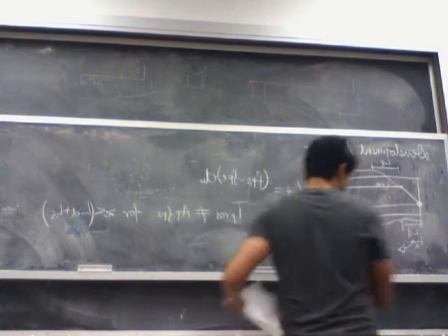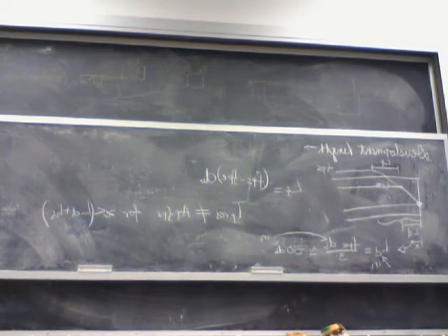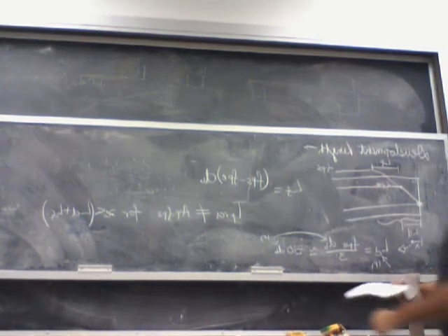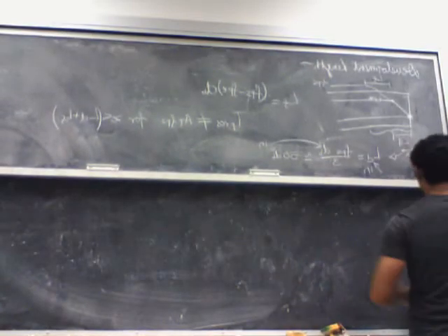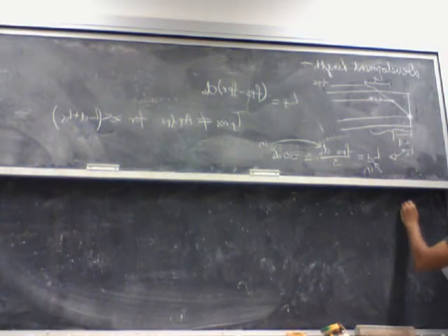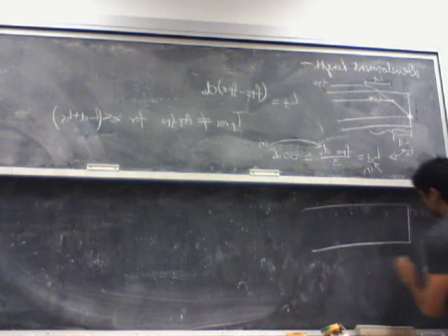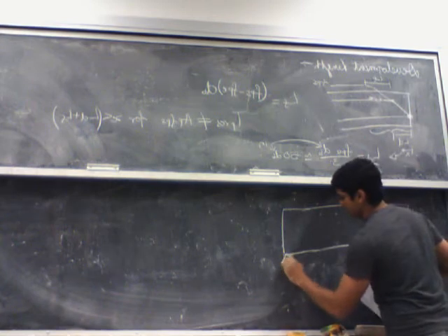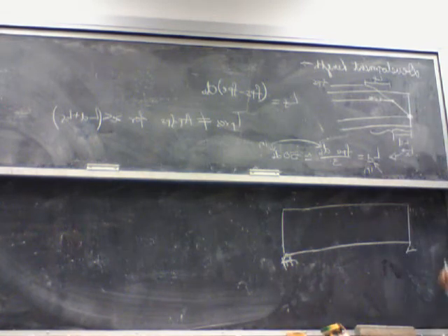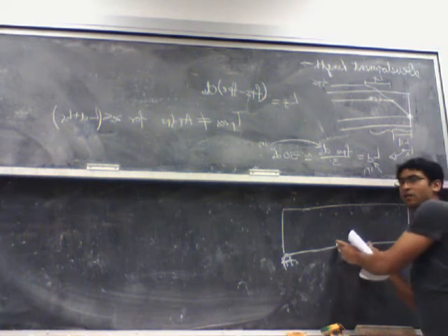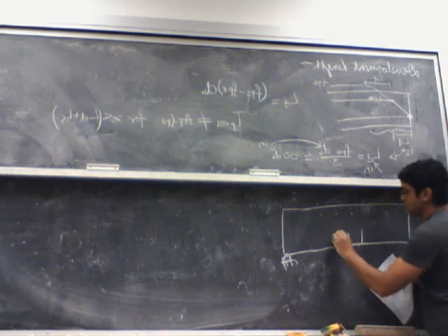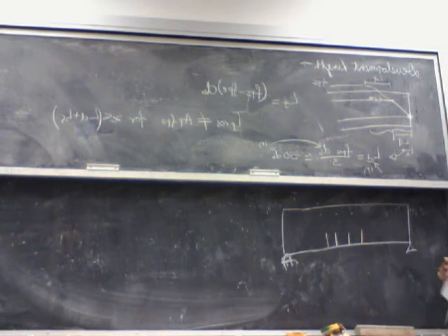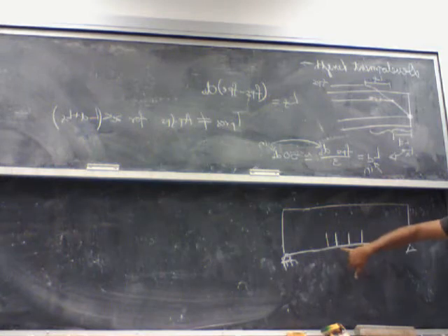So for the shear design, there are two kinds of shear failure in concrete. So if this is my, let's say, simply supported beam, and let's say if I have a uniform load on it, if I look at the crack patterns near the center of the beam, what you will see is cracks which are perpendicular. And these perpendicular cracks actually correspond to flexure cracks.